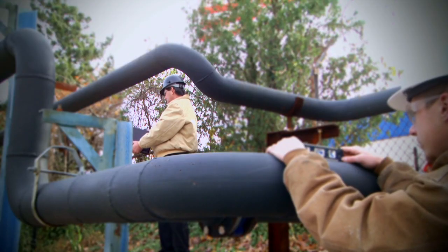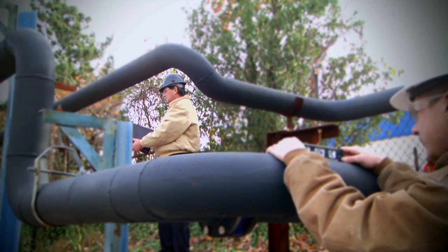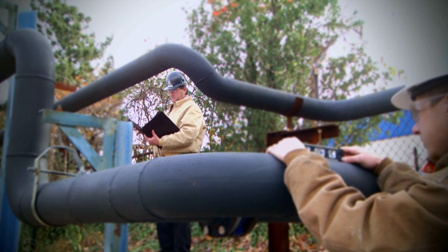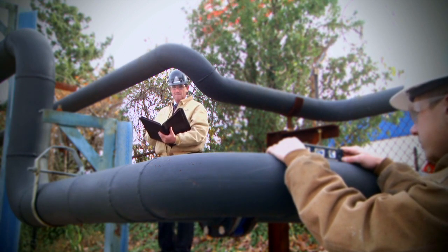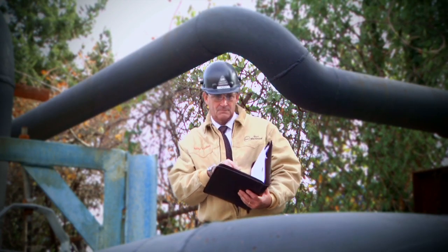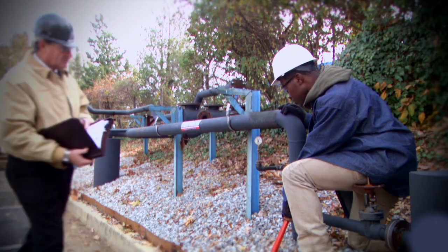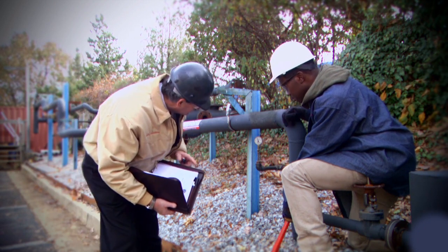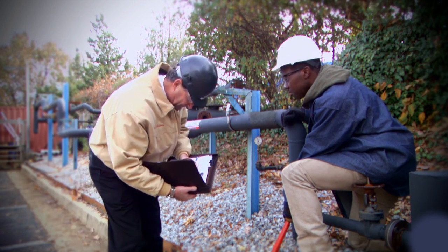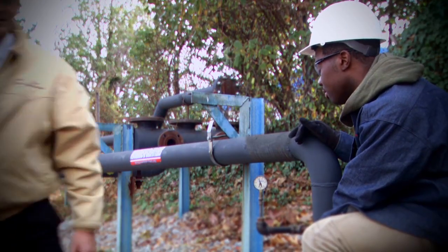The contractor is also responsible for examining the installed piping to be sure that it meets the requirements of the selected B31 code section, the drawings, and the specification. Finally, the contractor is responsible for pressure testing of the piping system, ensuring that it is leak-free.